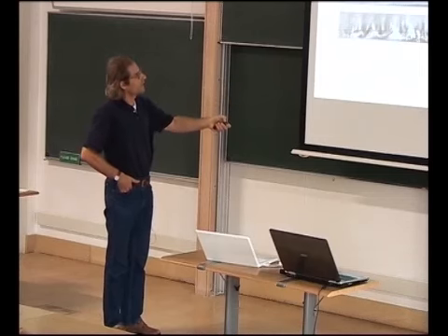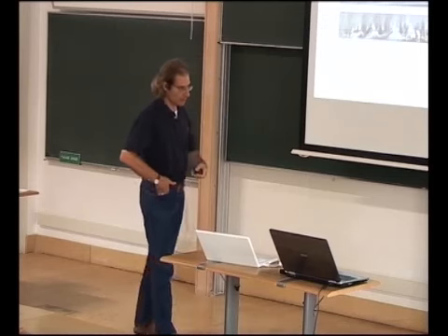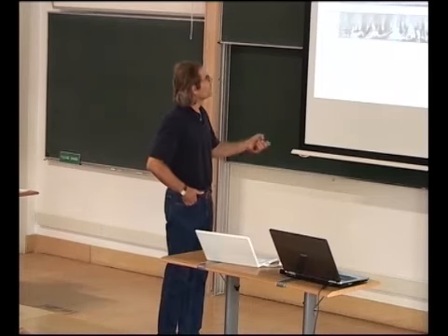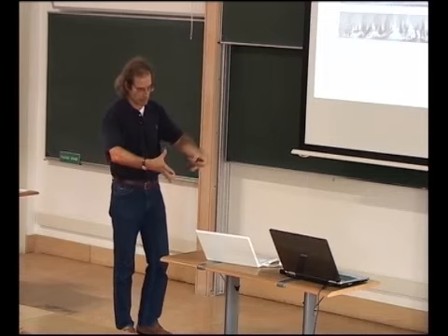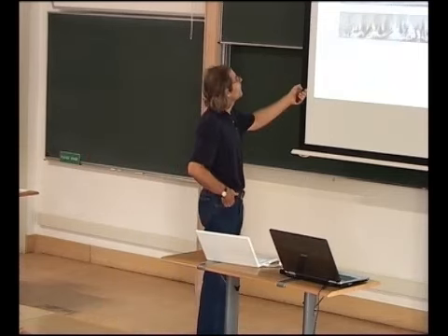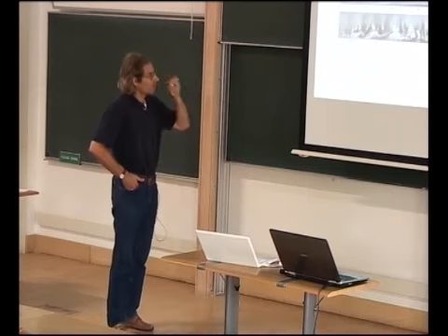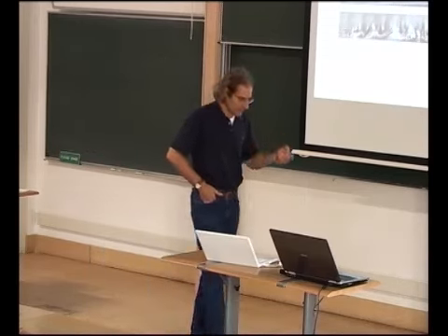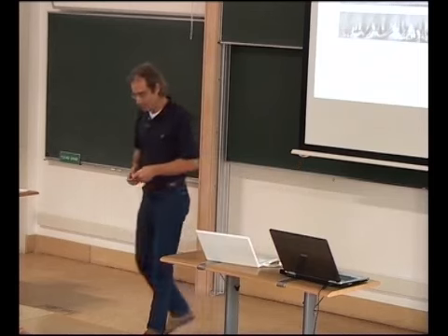So these jets, which are due to this displacement, this line of argument, these negative jets become unstable near the top of the boundary layer, break down, and at this stage, you're seeing a patch of turbulence filling the boundary layer. Experimentalists commonly look either at the wall or in a plane near the wall, and they see spots suddenly appear, apparently out of nowhere, but they do have an origin, higher up in the boundary layer. So the turbulent spots that seem to just appear next to the wall can be traced when you have a 3D DNS.